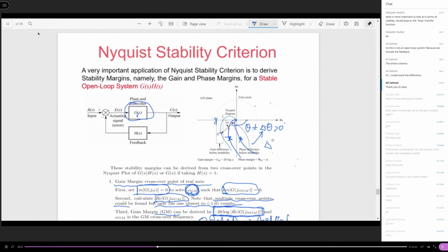You don't need to worry about it. But if you add a delta t that is less than 0, negative phase, then you actually push the crossover point going this way. So there is a chance that when you add an angle here, the crossover is going to be right at the -1, 0 point. Now you can see that this is going to be the critical case, just like the gain crossover case, right?